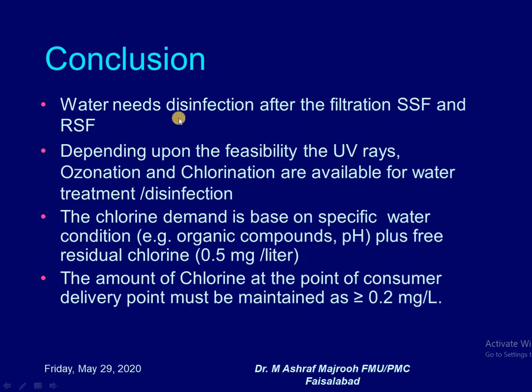As a conclusion, the water needs disinfection after filtration with slow sand filtration or rapid sand filtration, and depending upon the feasibility, UV rays, ozonation and chlorination are available for water treatment and disinfection. Any method which is suitable for the circumstances regarding the water sources and the technology available, these are the choices.